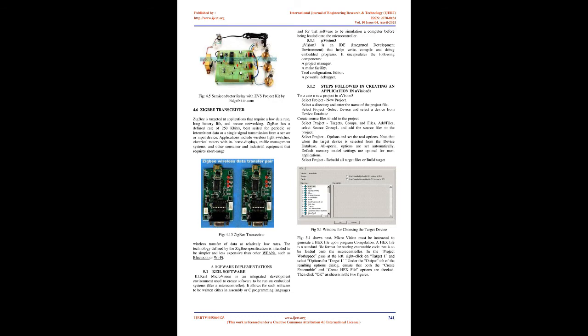It is a dual driver/receiver that includes a capacitive voltage generator to supply RS-232 voltage levels from a single 5V supply. Each receiver converts RS-232 inputs to 5V TTL/CMOS levels. These receivers, R1 and R2, can accept plus or minus 30V inputs. The drivers, T1 and T2, also called transmitters, convert the TTL/CMOS input level into RS-232 level.